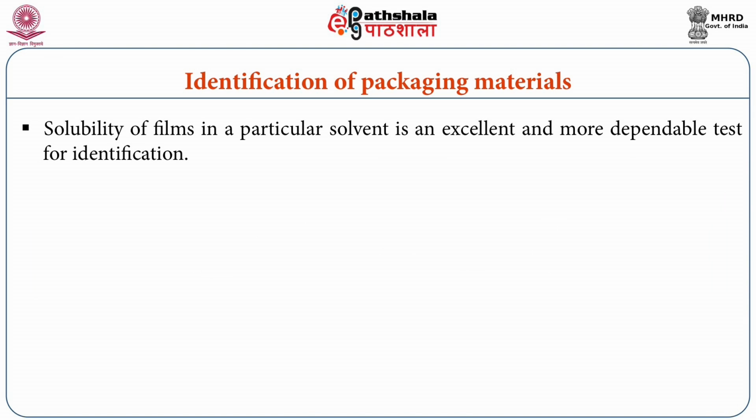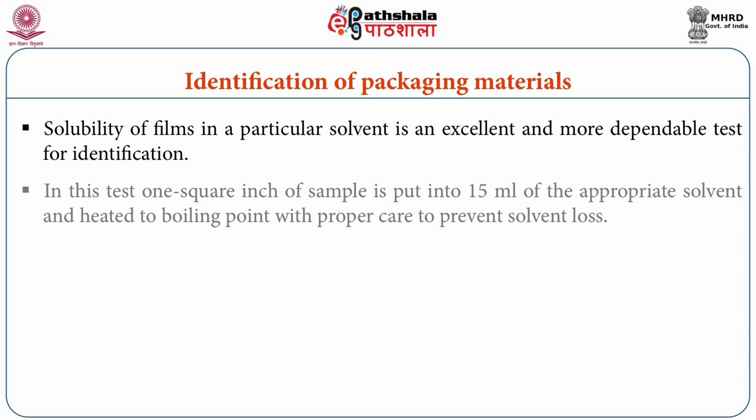Solubility of films in a particular solvent is an excellent and more dependable test for identification. In this test, 1 square inch of sample is put into 15 ml of appropriate solvent and heated to boiling point with proper care to prevent the solvent loss.